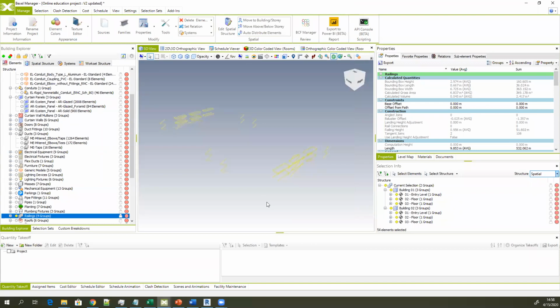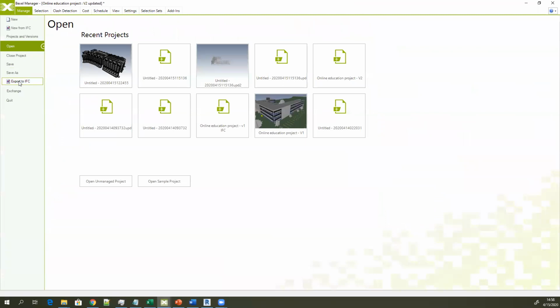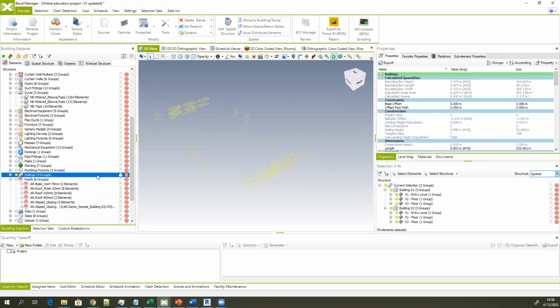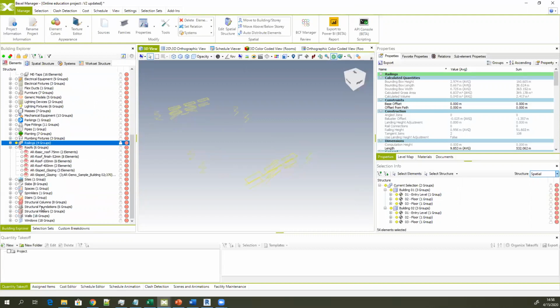Of course, the best way is now, since we have the export IFC option, if you edit some additional properties, you can export IFC files using the option to export elements to IFC. So in this case, in order to make it much faster, I can just export our, let's say, structural beams and these elements we added property for the railing.